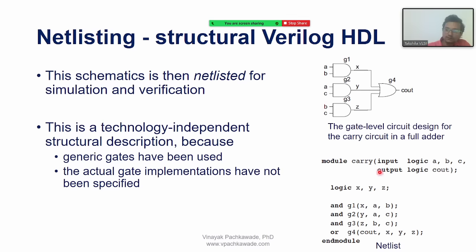For instance, when we write the RTL or Verilog code, structural or behavioral, the first tool we use is a compiler. It will compile it, just like we use a C compiler for the C language. Then it will generate the timing diagram for that particular logic. Then the designer will analyze whether the logic I have designed is working. Is it that logic or another logic or some error? It checks for timing and all this.